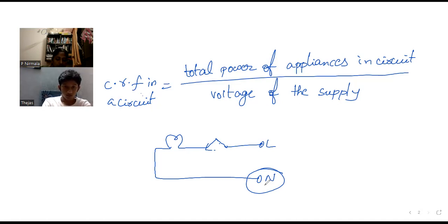This is also near the kilowatt hour meter. A hole 2 to 3 meters deep is dug in the ground. A copper rod covered by a hollow insulating pipe is inserted in the hole. A thick copper plate of dimension 50 by 50 centimeters is welded at the lower end of the copper rod and it is buried inside the ground. This is the way local earthing is done.